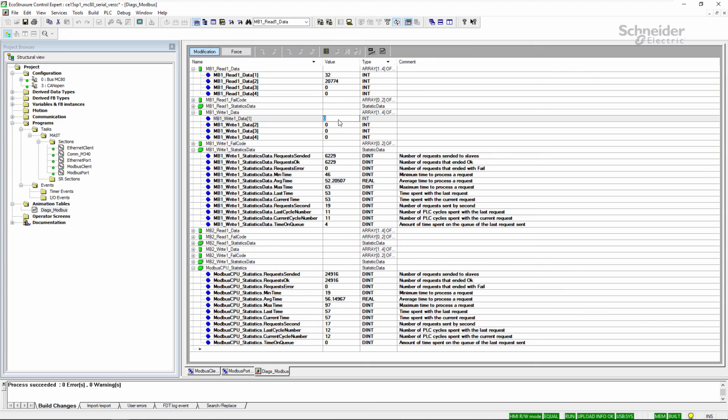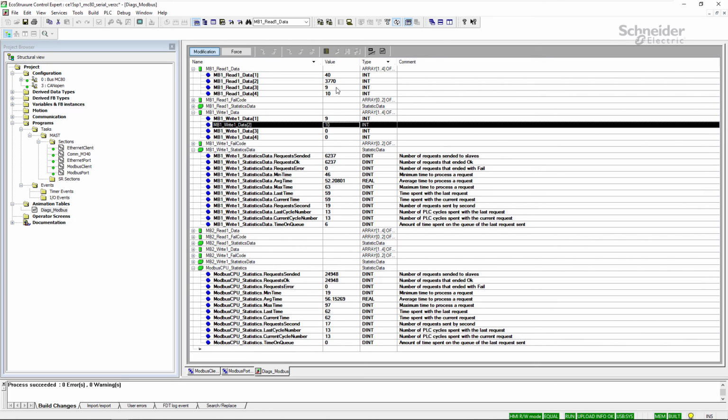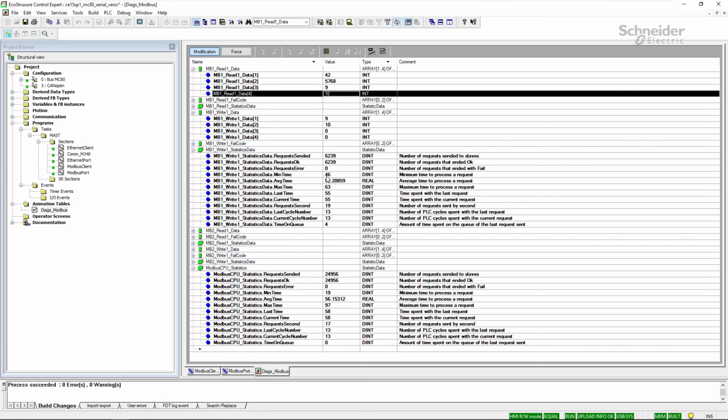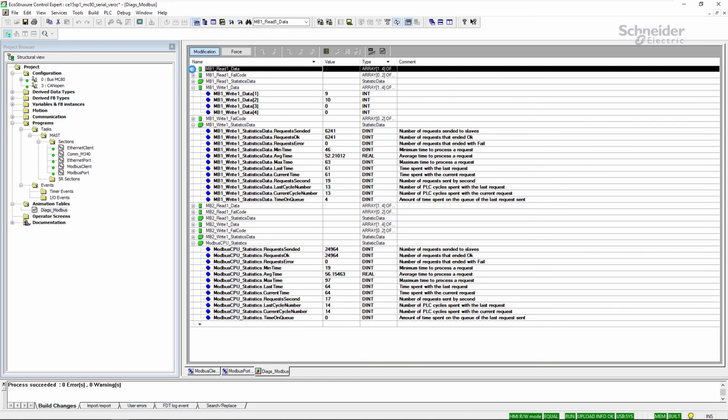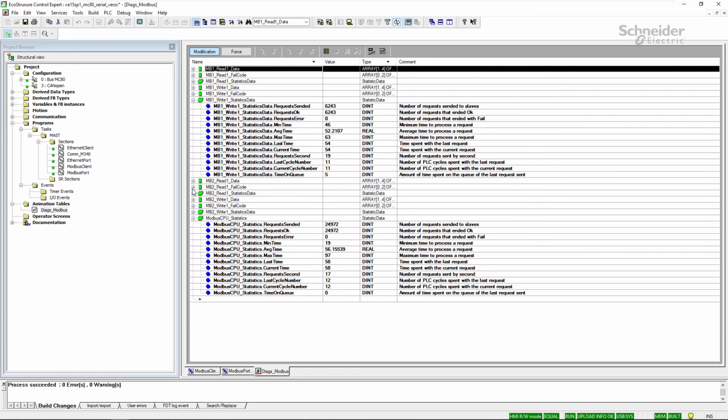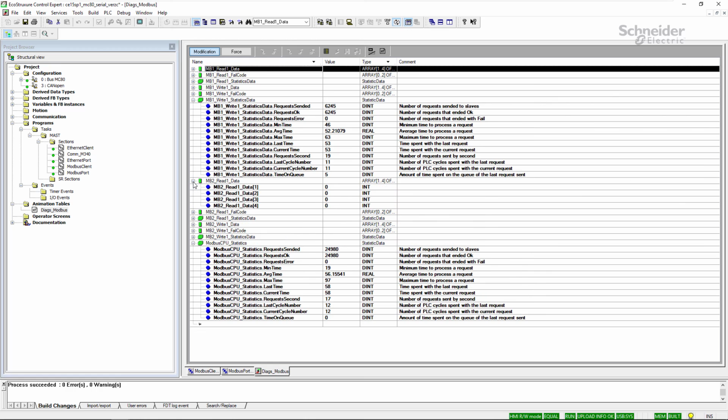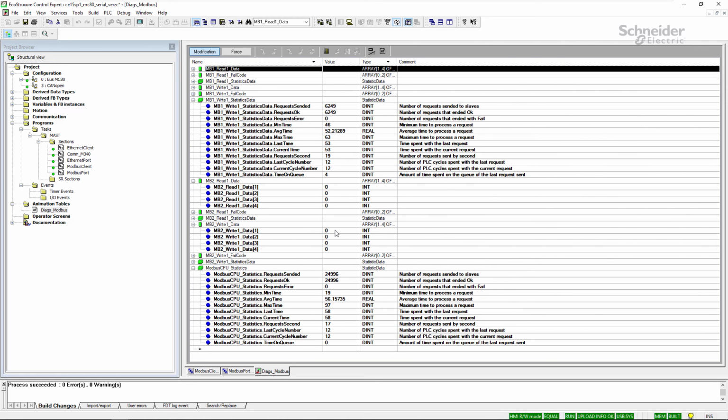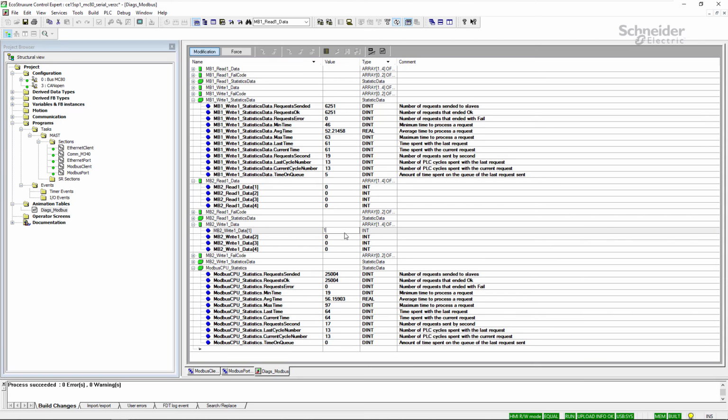And for this simple test, what I had prepared was logic in the target M340 controller, so when you write values to certain registers, they're going to be reflected in other registers that are being read by the MC80 master device. For the TM3 I/O modules, in a similar way, the MC80 master device is writing to the registers of the digital output modules, which happen to be wired to a digital input module.